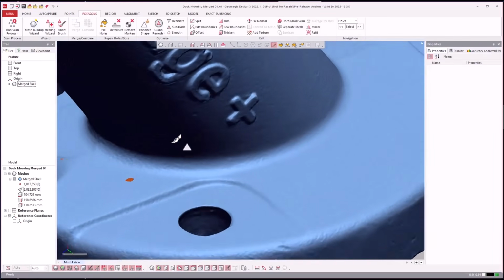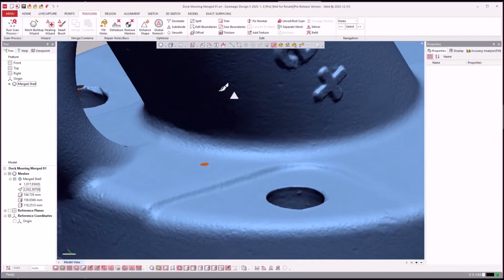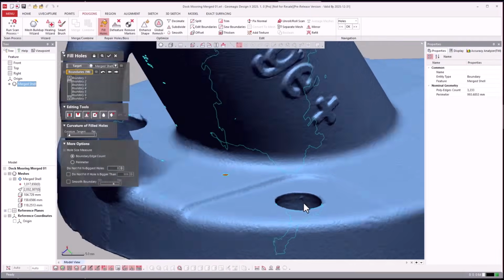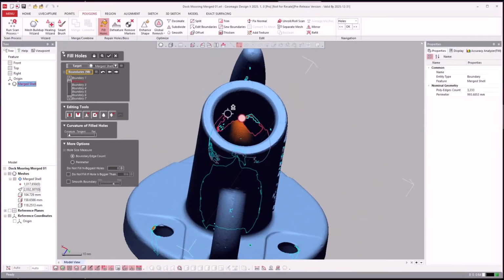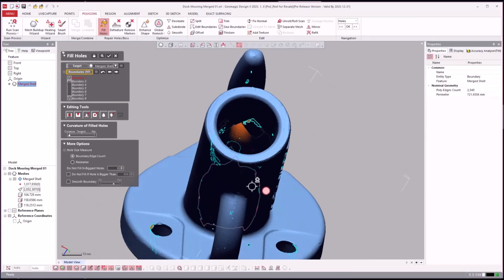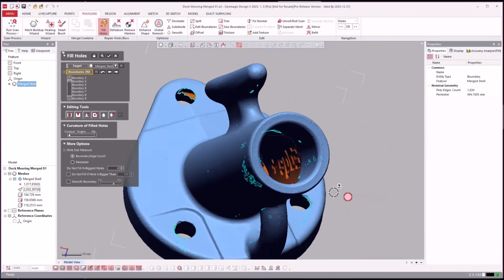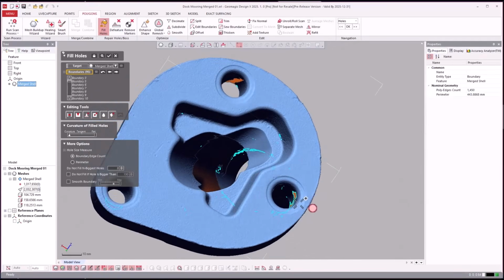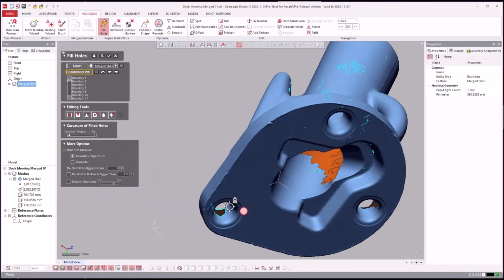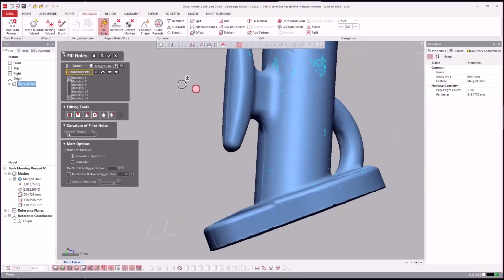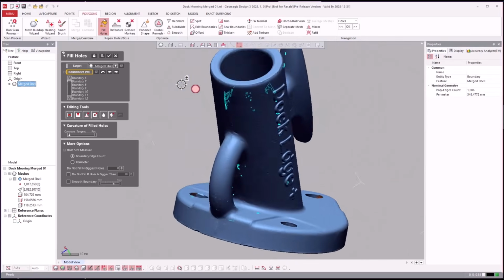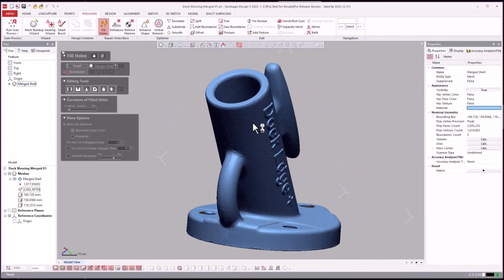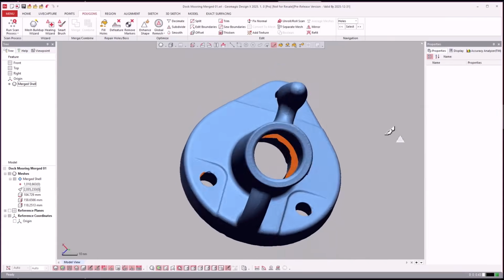So now I'll just go ahead and fill a couple of those little holes. You can also go into hole fill and say fill all, and then deselect ones that I do not want to fill. So if I visually see things that I don't want to fill, like these, like that. In this instance, I think that this will work pretty well. Just visually deselect things that I know I really don't want to fill. Tell it to fill all the rest. Does a lightning fast job there.